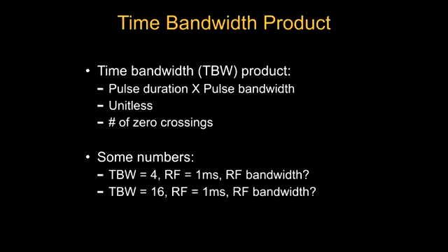So it's always a trade-off, and there's a cost to having high RF bandwidth too. I'll talk a little bit about numbers on that side, but in a practical setup, when you think about the RF pulse, you always have to think about the time bandwidth product. It's unitless. If the number is high, the slice profile quality is good. If the number is low, it's not a good slice profile.